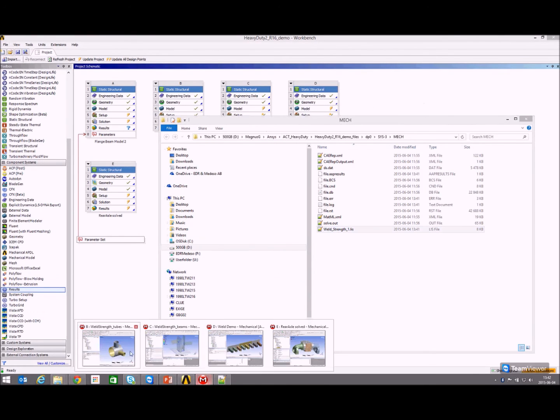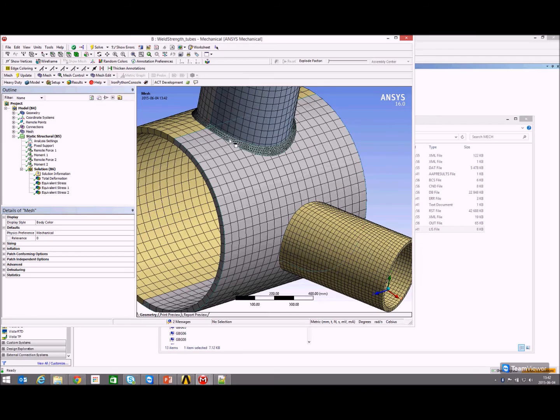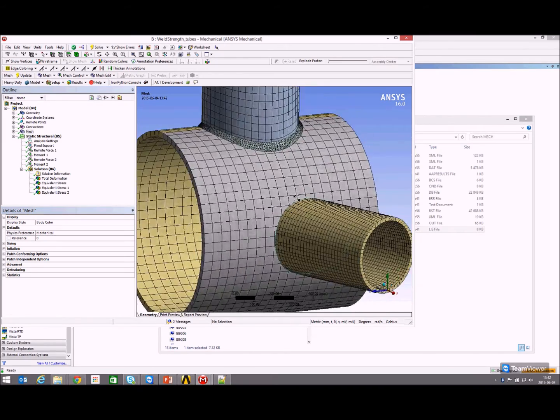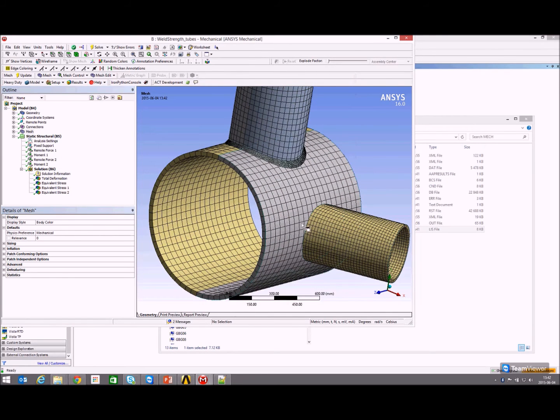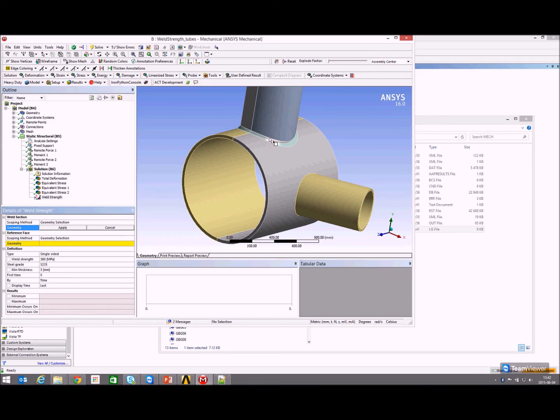Finally, you may also have a third kind of model, a pipe model, again using contacts, surface-to-surface contact or edge-to-surface contact. In this case, the edges are closed loops, but this will work even for this. Start selecting the weld edges. And again, selecting faces. It's important to select the cylindrical face attached to the edge. In this case, we see that there are 3 edges, but only 2 faces, but one face may have many edges.